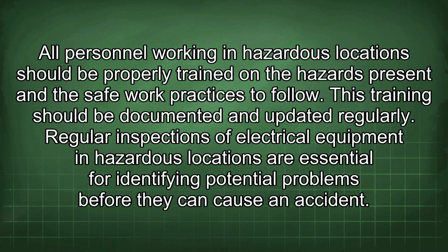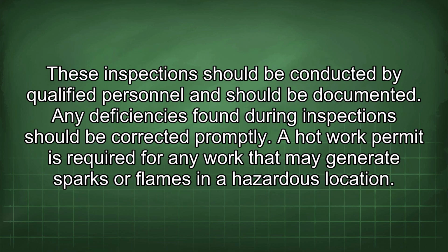Regular inspections of electrical equipment in hazardous locations are essential for identifying potential problems before they can cause an accident. These inspections should be conducted by qualified personnel and should be documented. Any deficiencies found during inspections should be corrected promptly.